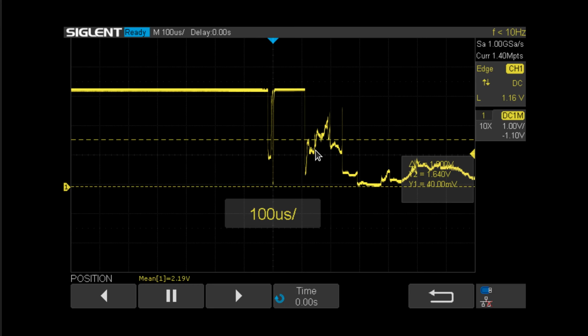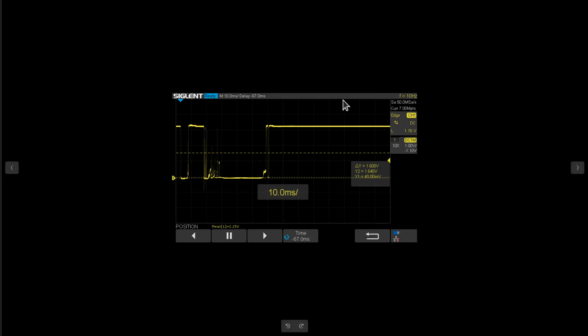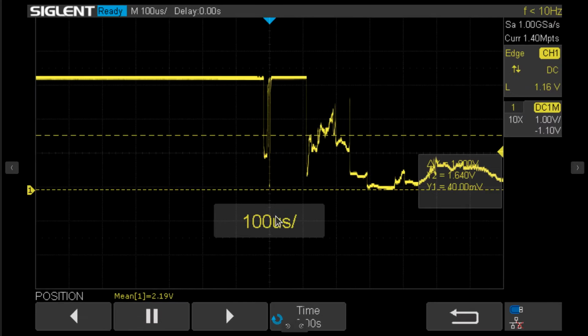Normally, you think of it in terms of the setup and hold time, but the setup and hold time is by definition violated already anyway. If you got high frequency noise, especially in the illegal area of your input voltage, this is really bad. Okay, so your synchronizer will help get rid of that noise as well. Again, that was a pretty high frequency. We're only at 100 microseconds here, so again, well, maybe 1 or 2 milliseconds of time would be good enough.